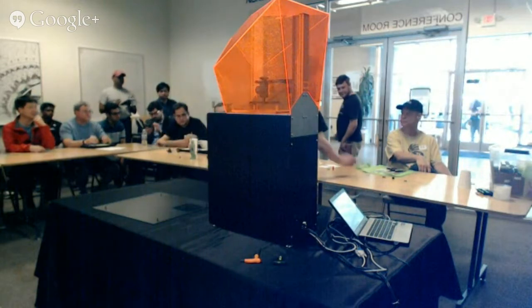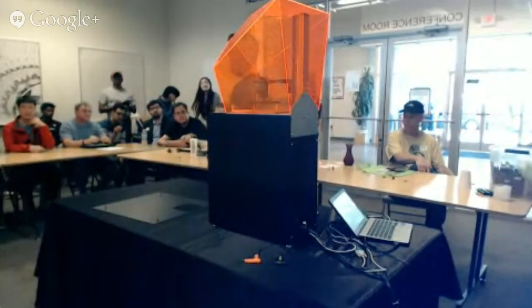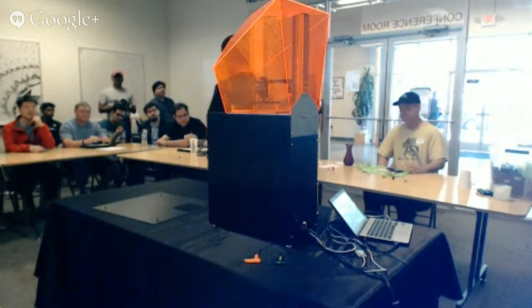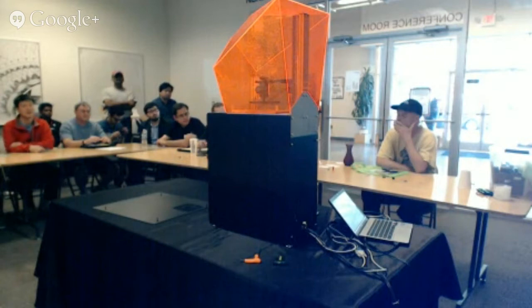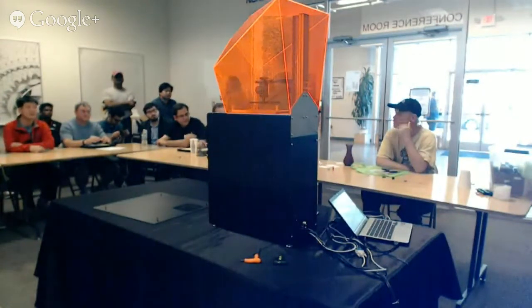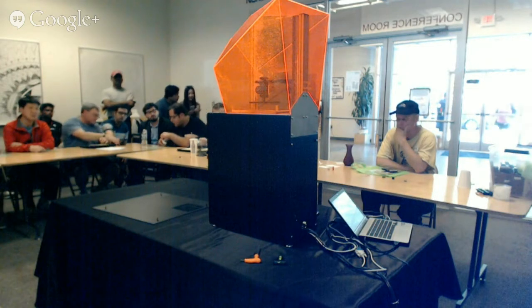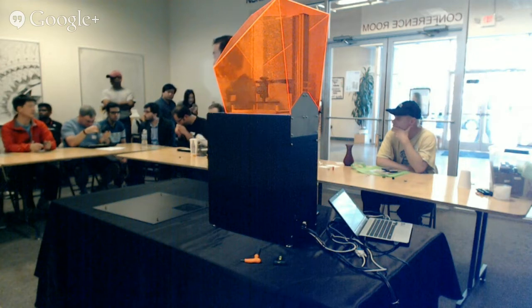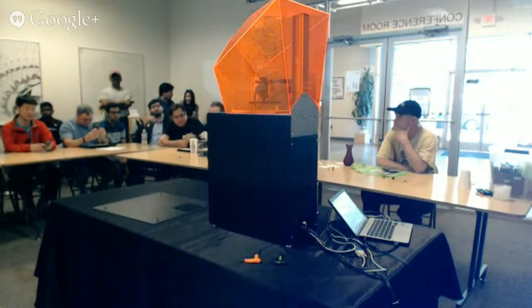And for functional use, we have ABS resin. So this is really tough. And there's one right there as well for molds and for more functional use. This is a screw right here. We're actually able to print threads for a screw with 1.5 millimeters. So it was really useful. That was for a person's thesis in a PhD program. It was a 1.25 millimeter pitch, 1.5 millimeter diameter.